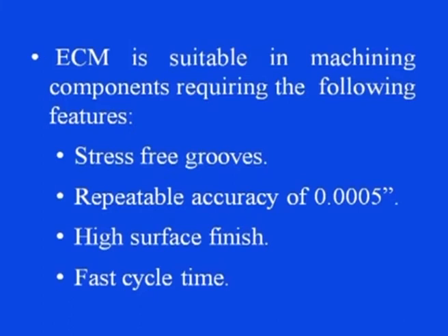ECM is suitable in machining components requiring the following features, like stress free grooves, as there is no mechanical machining phenomenon involved in this process. Therefore, mechanical stresses are not developed. Then repeatable accuracy, something to the tune of 0.005 inches. Then the parts where very high surface finish is required, at the submicron level, and where a fast cycle time is a requirement.